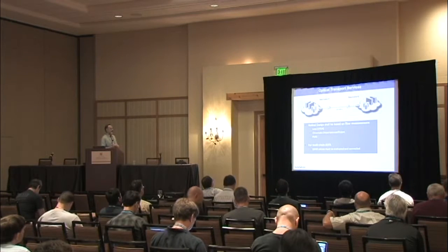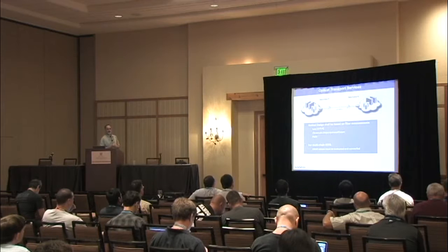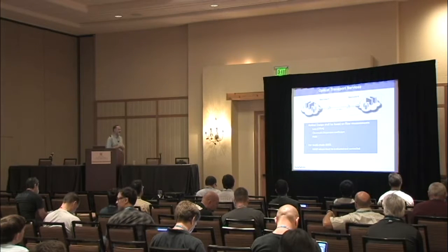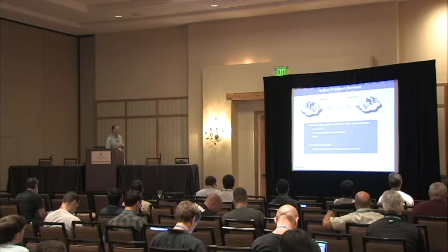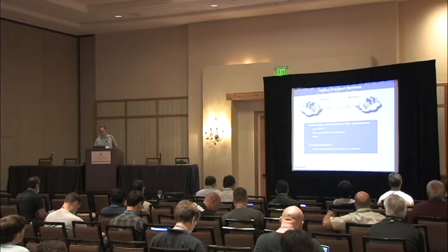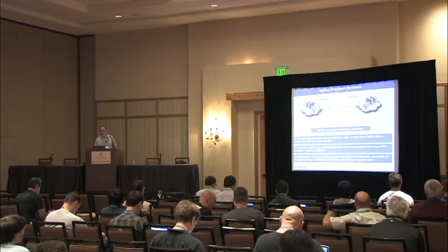In general, you must base your design on optical design and on fiber measurement. Do not just look at kilometers like we are going to do now. Measure the fiber, get an OTDR, measure your chromatic dispersion coefficient, measure your PMD. And for multi-chain EDFA, of course, OSNR values, optical signal to noise ratio, must be evaluated and controlled, and we are not going to talk about this because that's a little bit beyond this presentation.